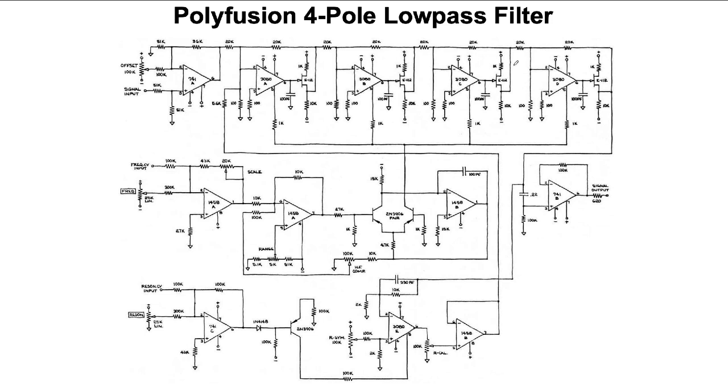So it's very important as we trace this through that we wind up going into the appropriate place. So since the entire structure is not inverting, the feedback loop here, if it's coming in the same direction as the input here with everything else, we need to find an inversion somewhere else. So let's double check that. So the output comes from here. This guy here isn't inverting, but it's not terribly important.